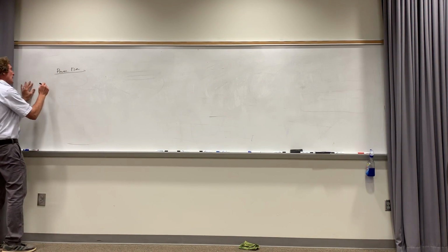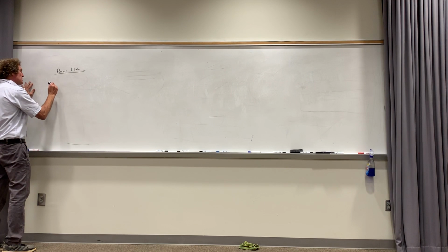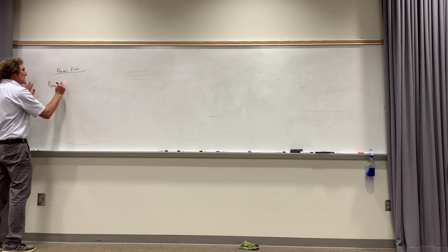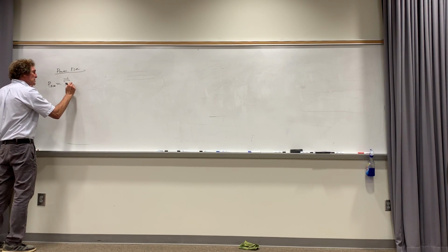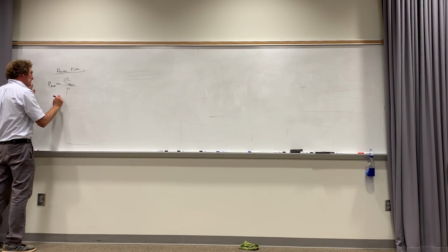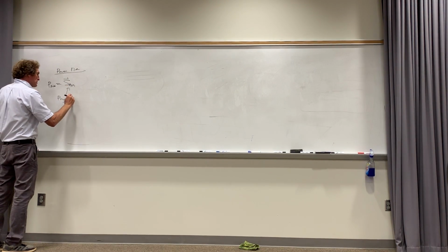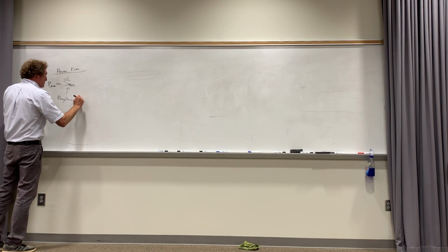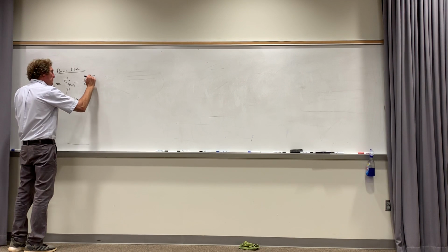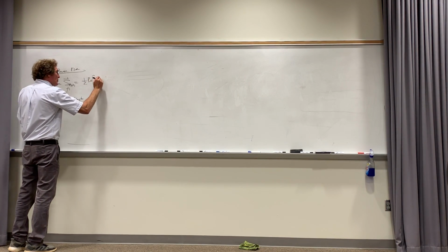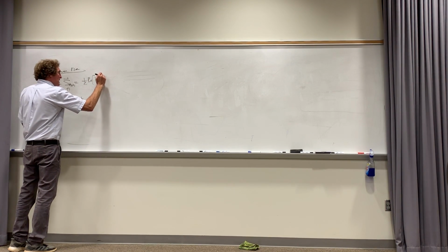Well, when you talk about average power flow, please just write this down, average power flow. The symbol is actually S_AV. He doesn't use it in his book, and this is called a Poynting vector. And that's 1/2, this is the definition, the real part of E cross H conjugated.